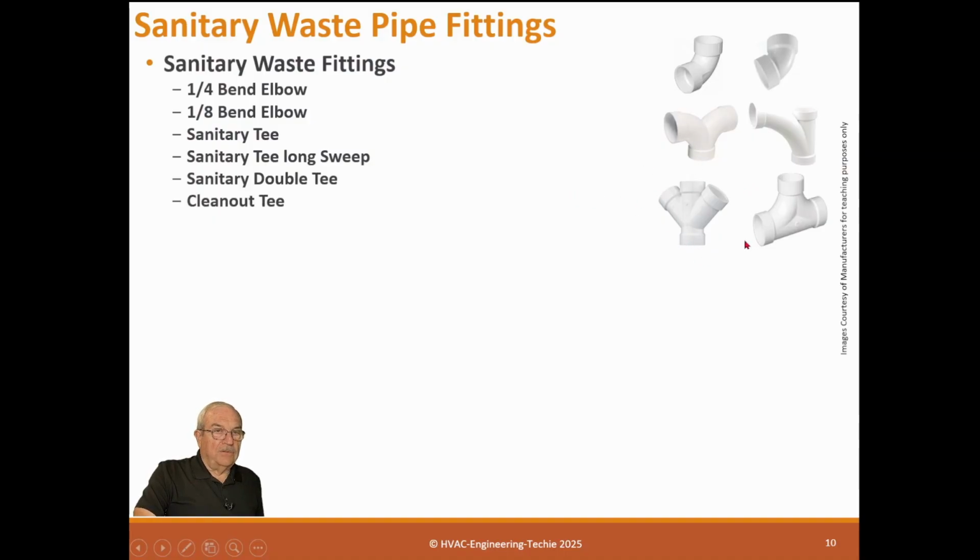Clean out tee. The reason this is a clean out tee is you put a clean out up here, and you can put the auger or the jet this way, or you can put it down that way. So you can go upstream or downstream, depending on what you're trying to unclog. So that's a standard tee.